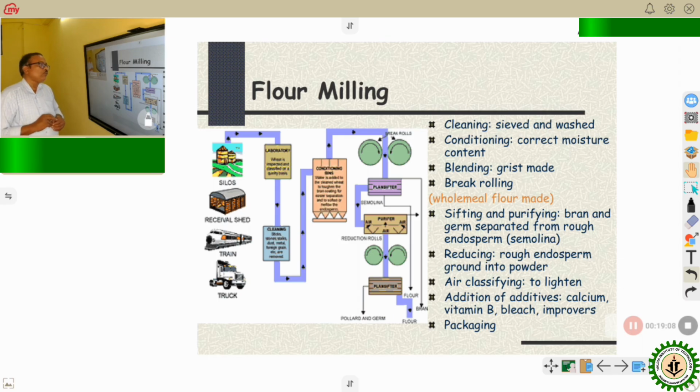Firstly, after the tempering operation, a 2 to 3% increase in the moisture content takes place, which is finally compensated when milling is over, because the milling process requires extensive abrasion and friction forces. Then that 2 to 3% moisture is removed during the process, and finally the product flour acquires the 12 to 14% moisture level, mostly the 14% moisture level. So that is one such requirement.